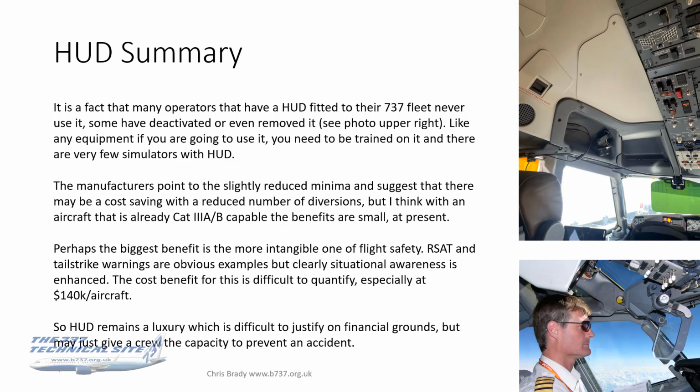I mean, you could argue that one-off training may be okay for just using it in normal line ops, but I would suggest that for doing LVP approaches, a similar level of training needs to be had that we do for LVP approaches with autolands. So a certain number of approaches per year in the sim and out on the line. That is never going to happen if the simulators don't have HUDs.